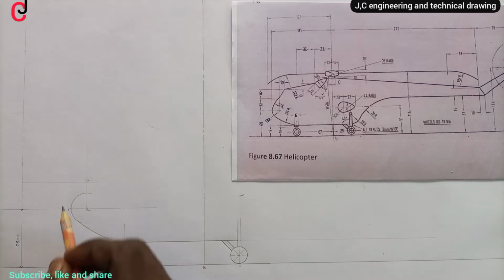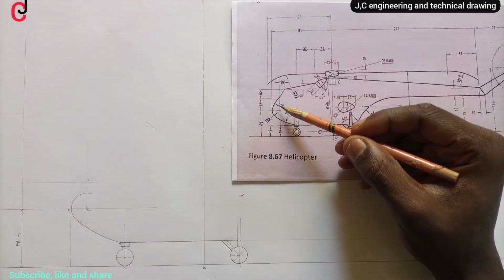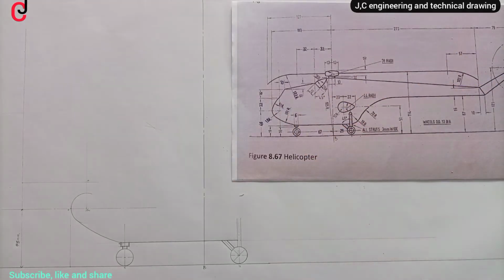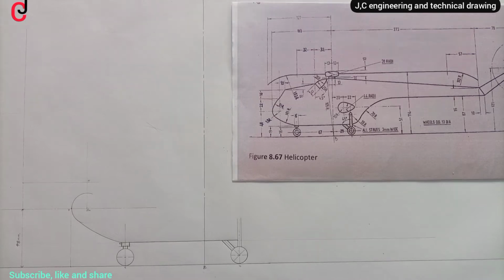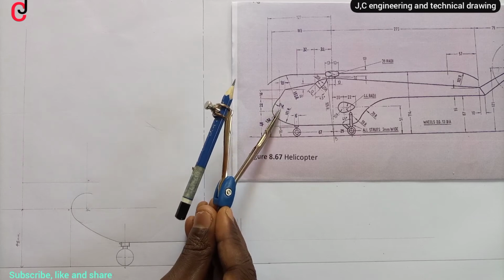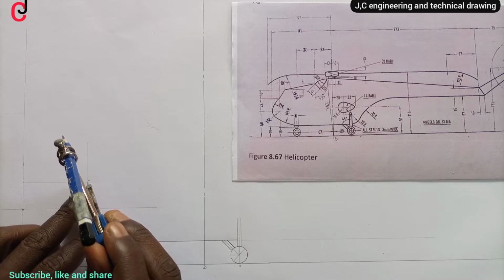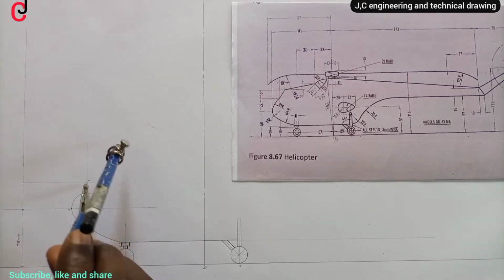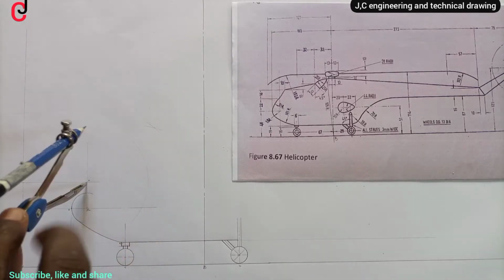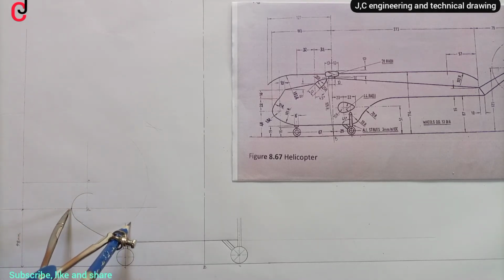Now using point O and point A, we should get an arc of 51 millimeter radius. So open our compass to 51 millimeter radius. So we succeeded in picking our compass to 51 millimeter radius, which is this. We'll place it at point A, scribe an arc, let it be a construction line, and then we'll place it at point O. We'll bisect the arc.